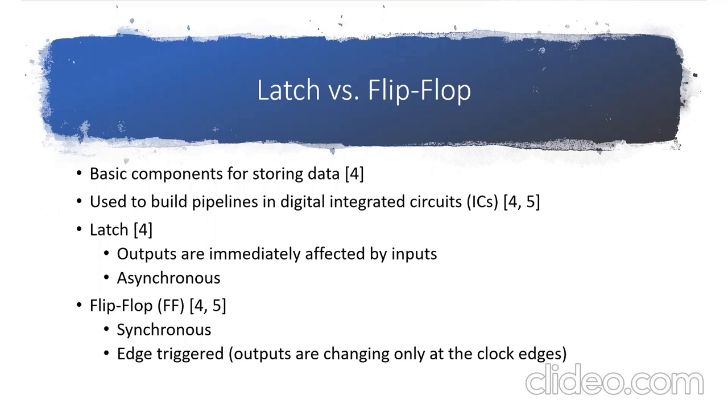Differences between latches and flip-flops are that the outputs of the latches are immediately affected by inputs, meaning that they are asynchronous. However, flip-flops are synchronous, and they are edge-triggered, meaning that the outputs change only at the clock edges.